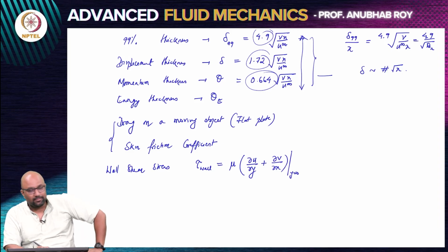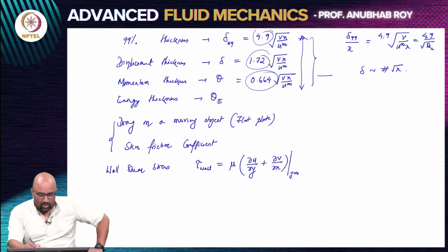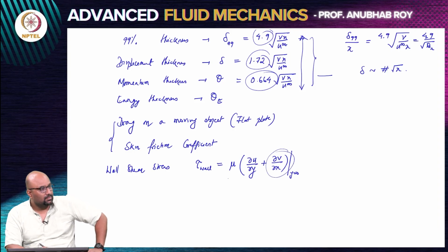This is tau xy or sigma xy. Now, do we need both the terms in the equation? If you remember in our channel flow, Couette flow problems, where we did fully developed problems, we didn't have this term because there was no vertical velocity, no transverse velocity in those problems. But here, we do have vertical velocities in the problem, right? So, shall we keep those terms? That is the question.